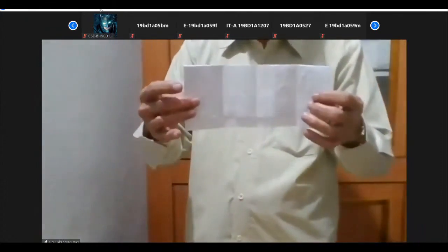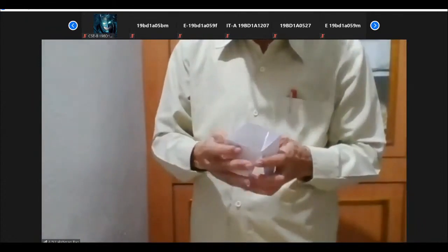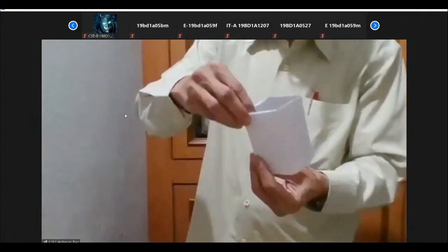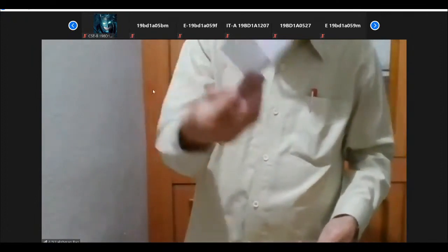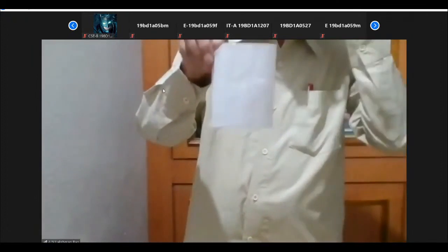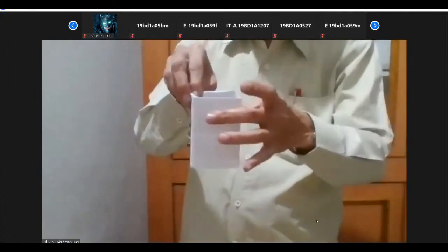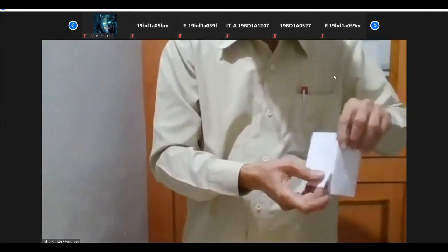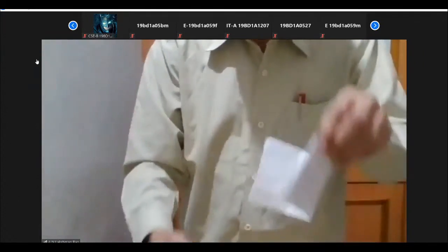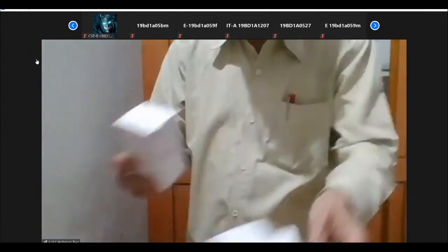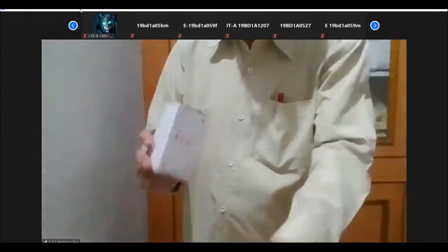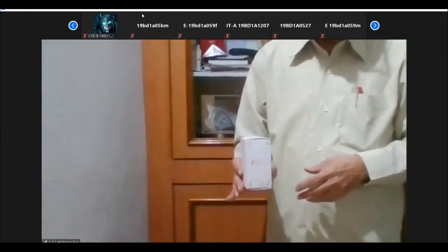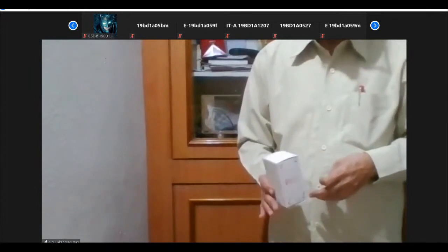It has got 4 faces now. Now, if I fold it exactly at all the places, I get a hollow rectangle. This is length, this is breadth. Again, back side, this is length, this is breadth. The complete lateral surface area is covered. That area is called the development of the solid. This we are going to draw.